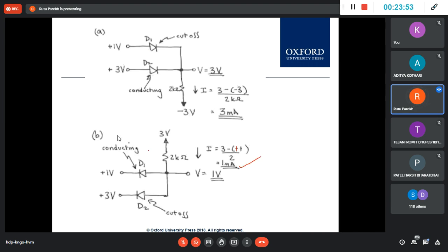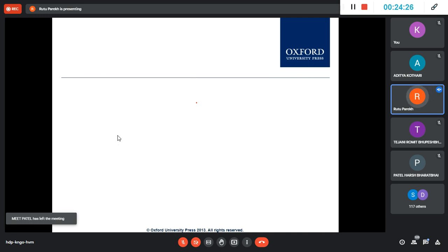So when you see both are conducting, but once this starts conducting a little, as I said, the voltage will appear here. This will be short since it is an ideal diode, and this will get into cutoff. And similarly, once this is conducting, 1 volt will appear, so 1 volt is here and plus 3. So this will make that go into cutoff. And so these are gone, they are driven into cutoff. Initially it may seem otherwise, but once you turn it on, it will get into cutoff.